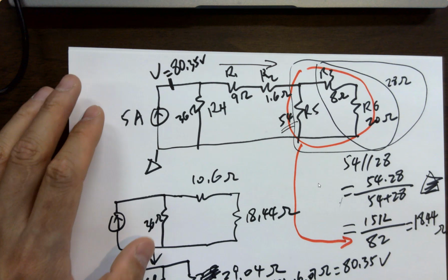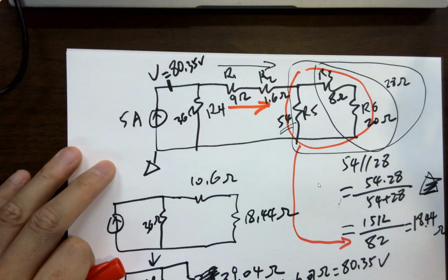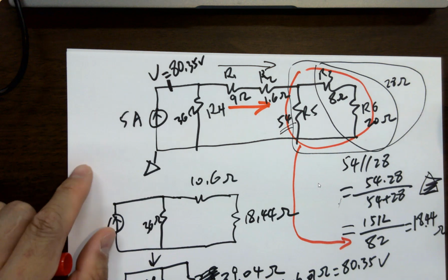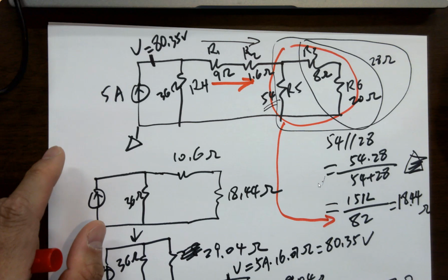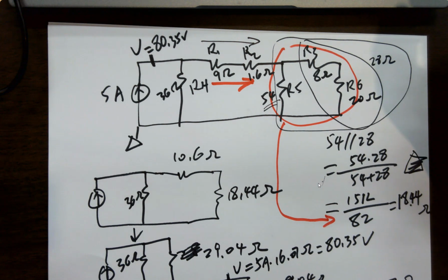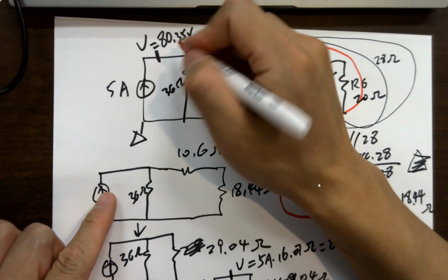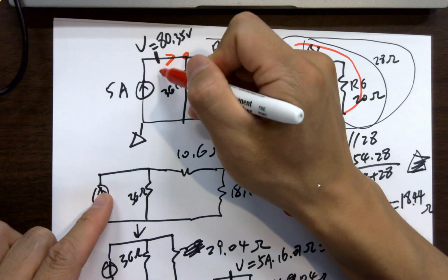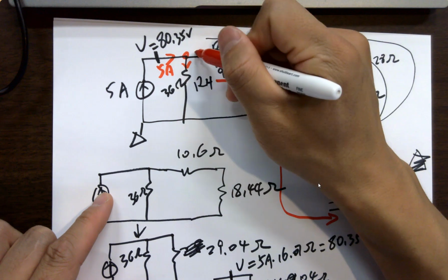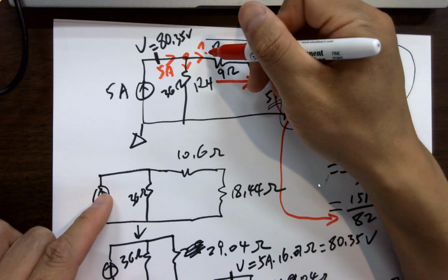Right? It's asking for the current here. The current here. What's next? What's the next step? Which circuit law you want to use? Circuit series? Yeah, but which one? KCL, KVL, Ohm's law? KCL, right? You got here one current comes in, which is 5 amps is given. Split into two currents, and this is what the problem is asking for.